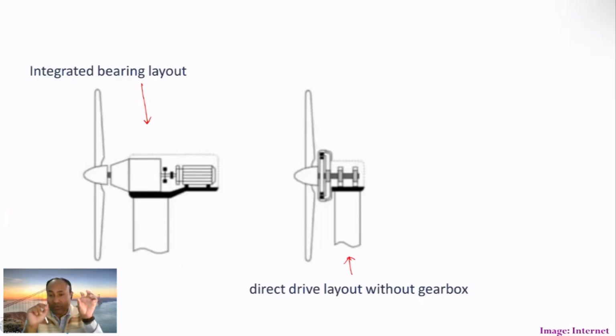The reason is that all your rotor blades, which are really large in size, are connected with the low speed shaft or main shaft. There the RPM is very low, but that shaft is exposed to heavy torque or dynamic loading, because when the blades rotate, depending on the wind speed or wind gust, even a small offset in the motion can increase the loading on that shaft.